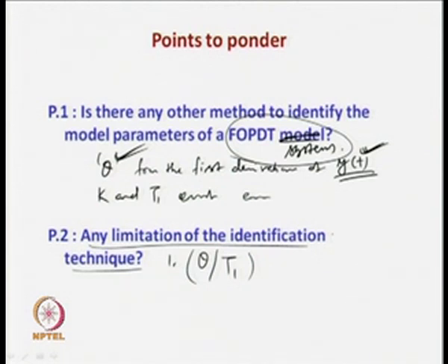Secondly, the sustained oscillatory output must be noise free, otherwise it will be very difficult to make measurement of the slope, which is an important parameter and whose expression has to be used to estimate the 3 unknowns associated with the transfer function model.